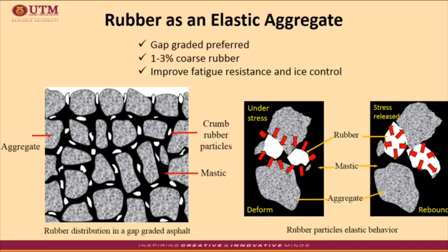Initially, the dry mixing method incorporated crumb rubber into gap-graded mixtures. The target was to control the effects of snow and ice on pavement surfaces. The rubberized asphalt mixture was expected to have the advantage of breaking up ice and providing better skid resistance during icy conditions than conventional asphalt mixture. Previous studies observed that the incidence of ice cracking increased when the percentage of coarse rubber added to the mixture was increased.